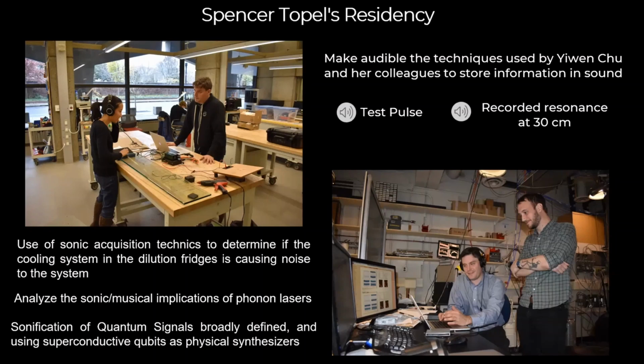And so you can see here, there's a big glass plate, and we put a small piezo actuator on it, just a disc, and it just created a small ping. And then we recorded that resonance, and it doesn't sound like much. It's just a bleep. Okay. So we basically have this small pulse, and what we found when we looked at the two waveforms together is that they strongly resembled what they saw inside the fridges, that you had an extended resonance as a result of the glass plate. It was very similar to the device they used in the fridge.